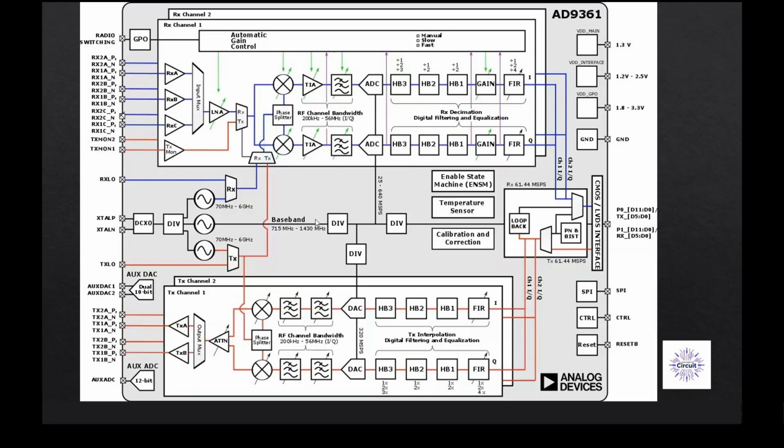Before that, I just want to also go over the idea of how we can make beamforming. Because as I mentioned, we need to create a delay or a phase difference between our TX channels or RX channels when we are making beamforming. But how can that be done?